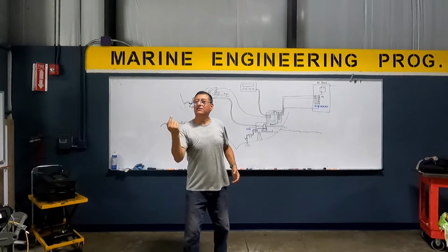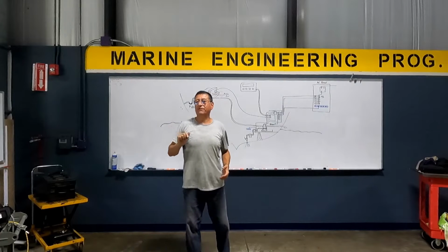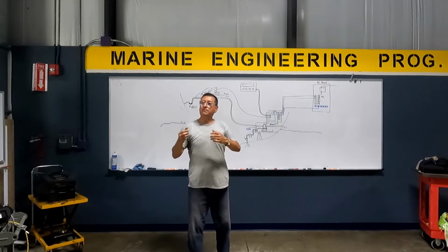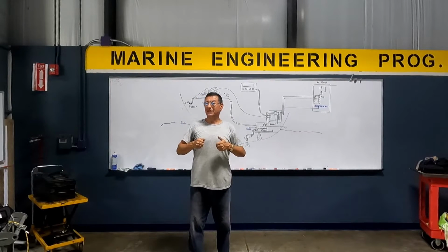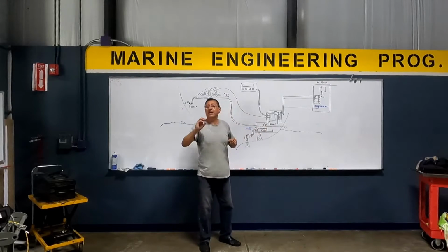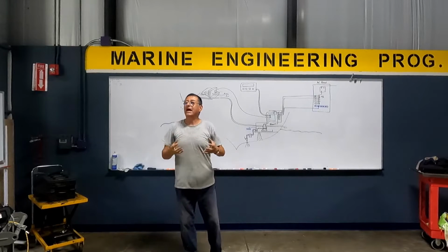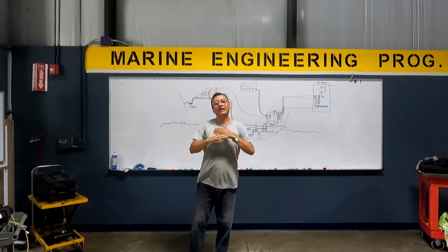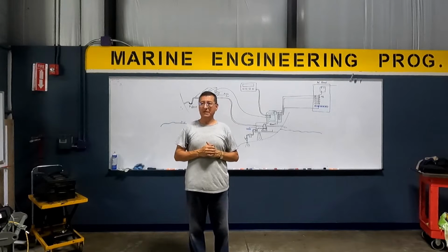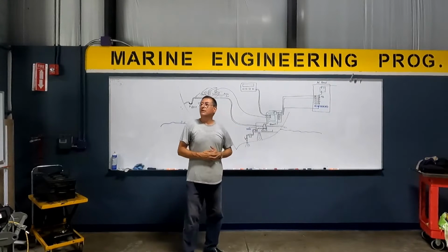In the condenser is flowing high pressure refrigerant. You remember? High pressure refrigerant. If the temperature of that pipe increases, the thermal switch, the high pressure switch located in the high pressure pipes, opens and interrupts the current in the compressor, and the compressor stops. Anybody follow me? That's the function. Okay.